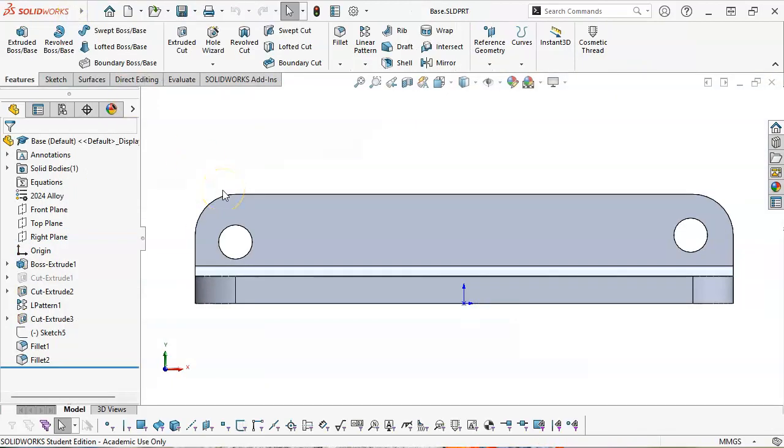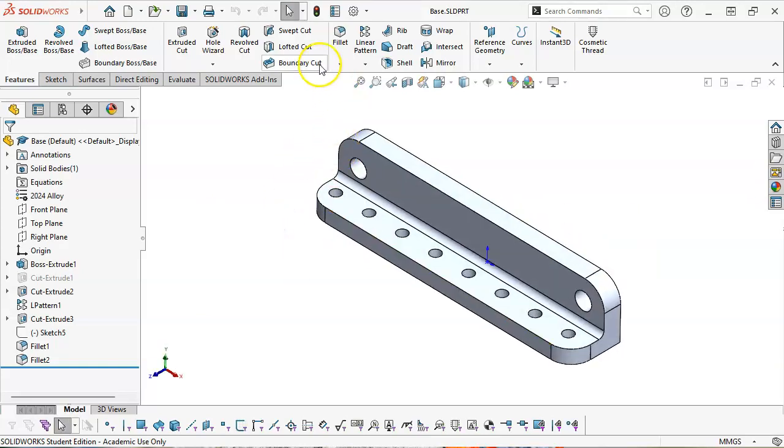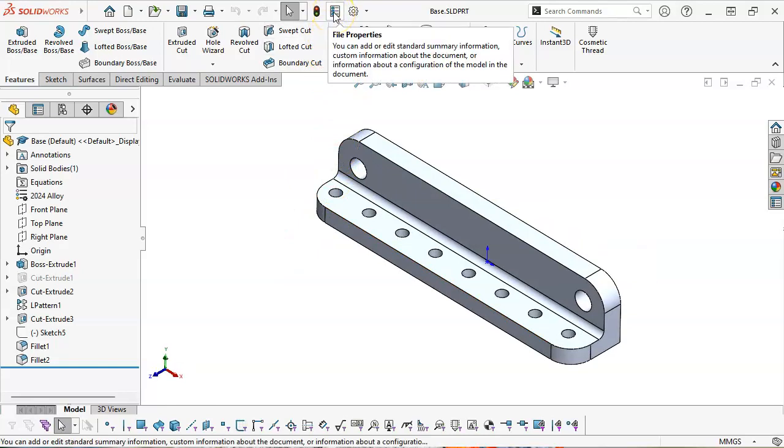So what we'd want to look at is possibly making the pins out of a steel or stainless steel and pressing a bronze bushing in. Again, we don't really have a full specification that says this many RPM. It's going to perform these functions. So that being an unknown, we'll add that to our list of questions for the next design review.